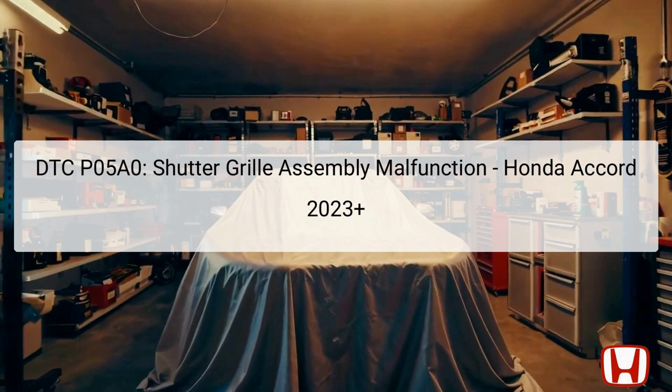The DTC P05A0 indicates a malfunction in the shutter grille assembly in the Honda Accord 2023 and newer models. This code arises when the powertrain control module, PCM, detects that the shutter grille system is persistently in a stuck condition, even after attempts to redo the initial learning for the system have been made.